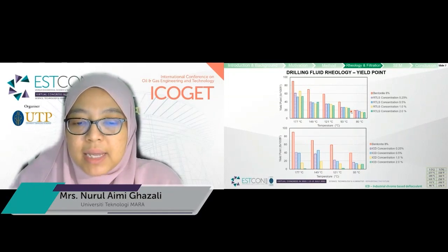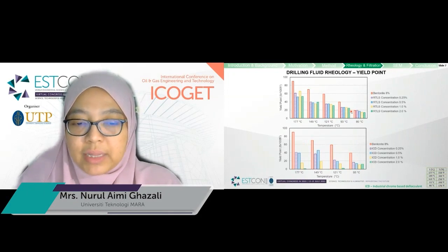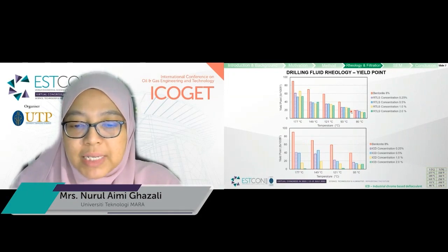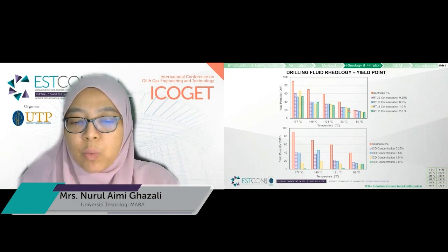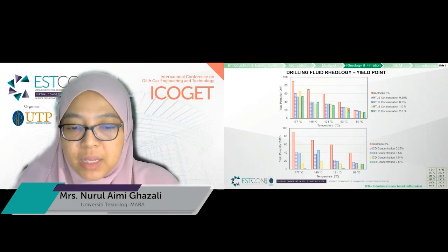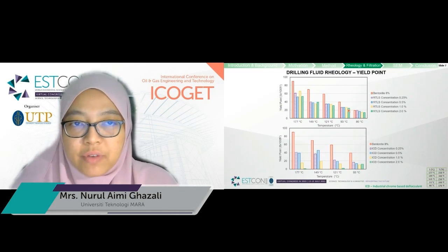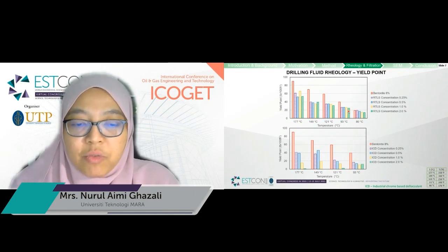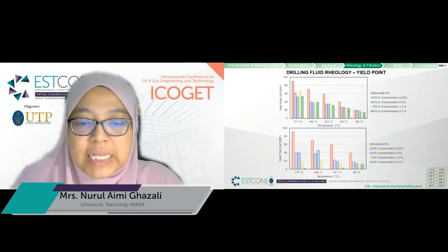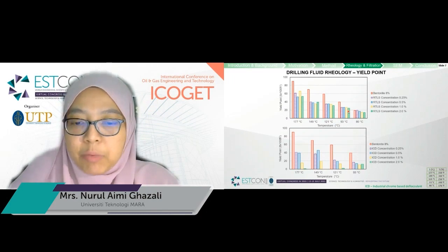Clay platelets that link to each other increase the yield point when flocculated. Chemical treatment will neutralize the clay platelets and reduce the yield point, but once the condition is accomplished, further addition of chemicals does not reduce the yield point. So there is an optimum concentration that works best to produce a good yield point. Removal of colloidal solids is needed when we want a further reduction of the yield point.